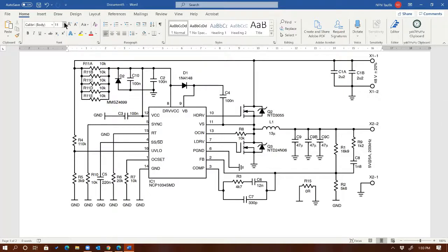And I like the way they draw the schematic, because you can see the way they draw the signal grounds different from the power ground. I don't know if you noticed that. And then they connect the two grounds, the signal ground and the power ground, with 0 ohms resistance. I like that. And then Nick, you asked about boost.